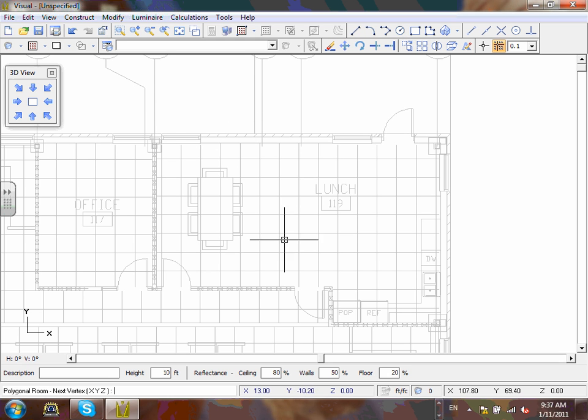Now, if you grab a line like this, you need to go ortho always. So here's my ortho. See where my ortho is? Everybody see where my ortho is? Click ortho. Everybody's got the ortho? Right in here, hit ortho, and grab. So I grabbed one corner, and just trace the room, guys, one corner to another, to the best of your ability. Don't sweat it too hard if you didn't catch the exact one.